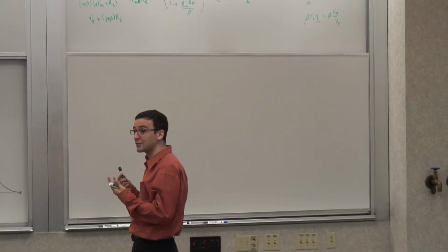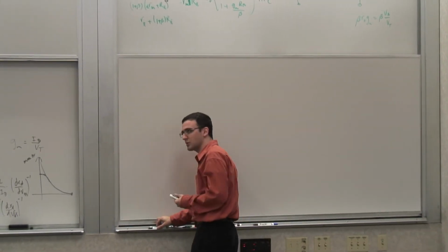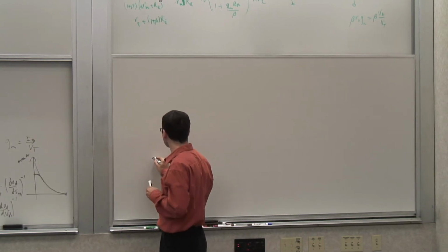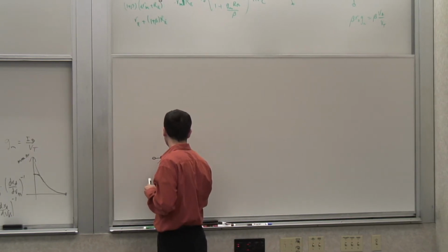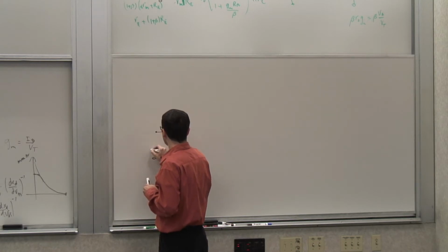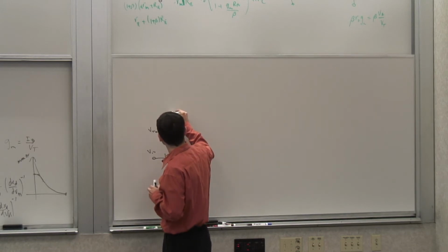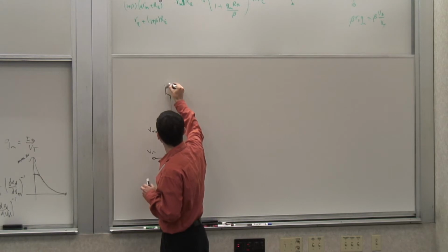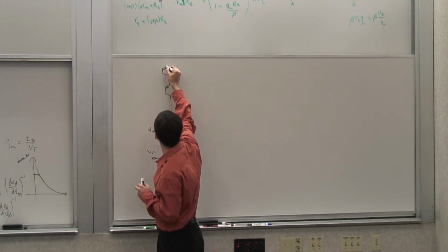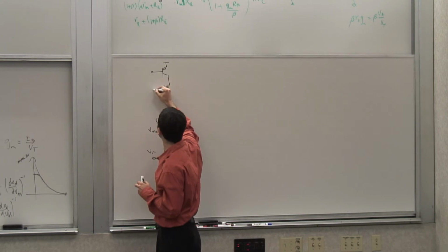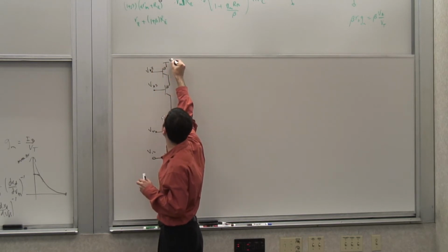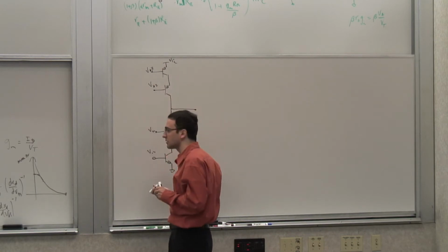But then we saw we could go actually beyond that by introducing a cascode current source. So one of the things that we could make, for instance, was something like this. You can have a cascode stage, so this would be the input, a driving stage, and then it can go to a load that can be formed by a cascode of PFETs, PMOSs, I'm sorry. I'm taking the output from here.